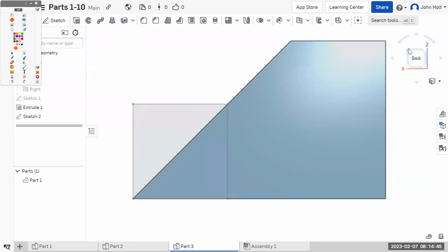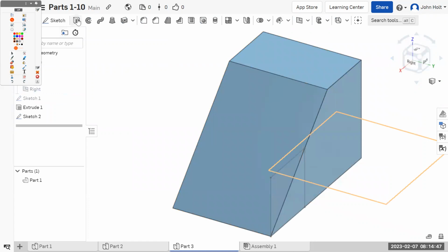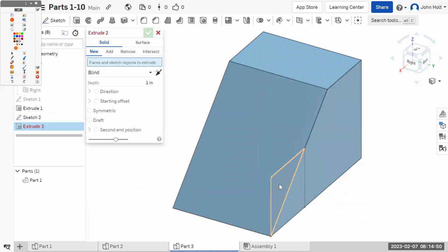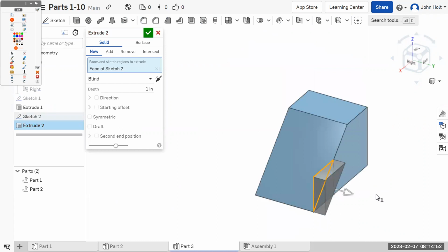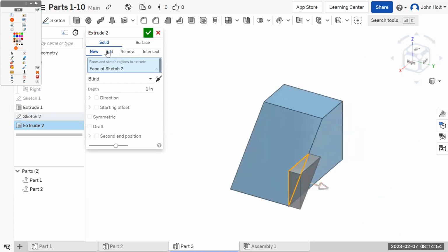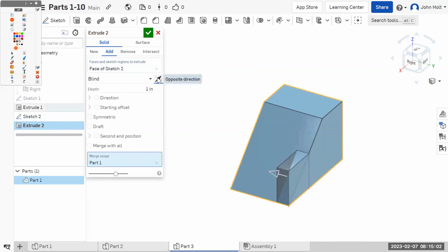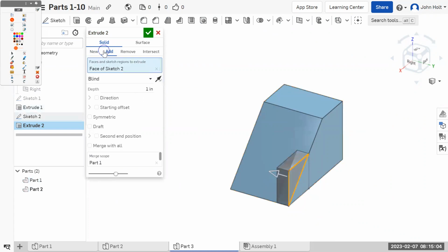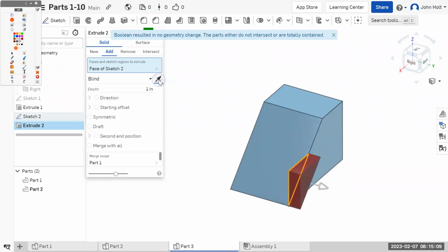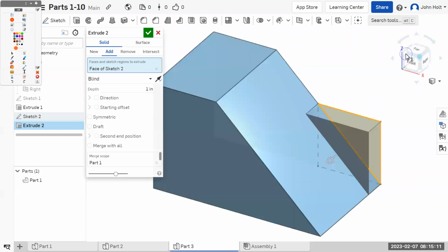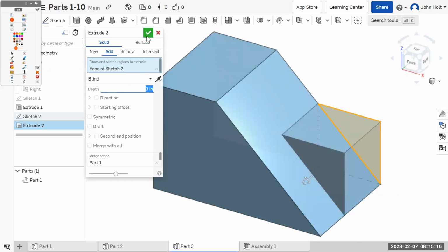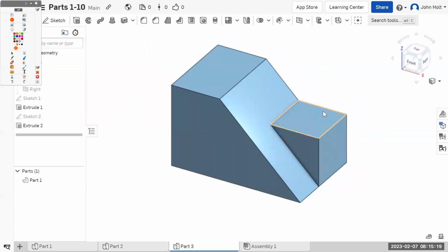Finish the sketch, look at it from some corner, and extrude. And we can actually just extrude the bit there. You do need to switch it to add so that it doesn't, hold on, let's see here. Can we switch back? Good. Okay, so you need to switch direction. I don't think new will work, but switch it to add and make sure you're going towards the shape. And we want to add 3 inches to the front. And there's part 3.